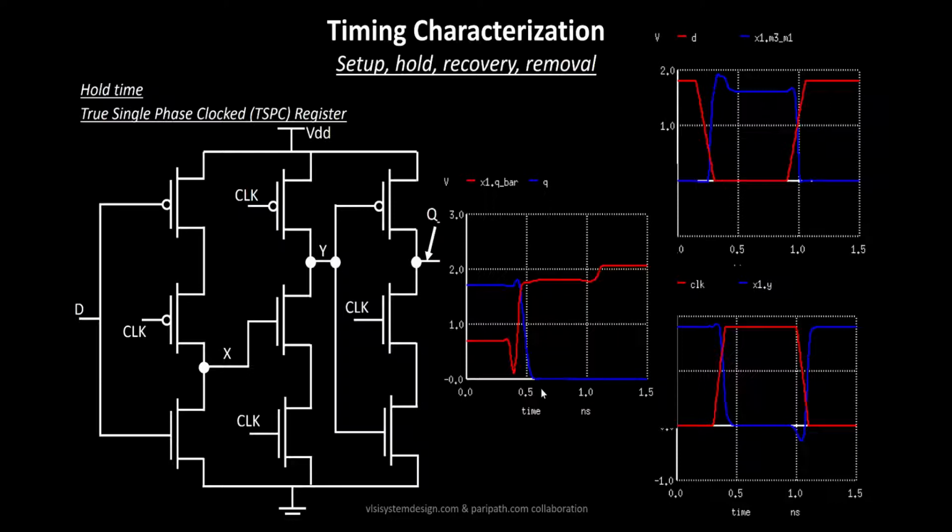Now there are some setup time and hold time associated with this particular waveform. The moment you send the rising edge of the clock, you need the waveform to be changed within a certain window of the clock.